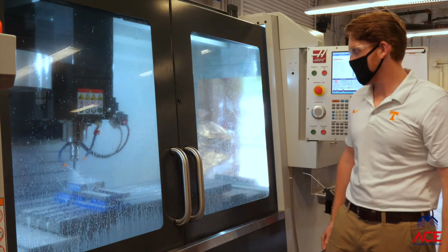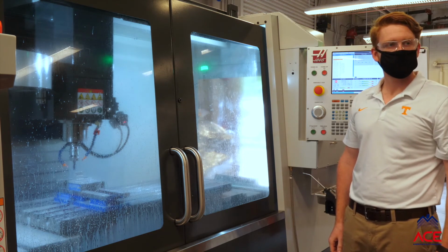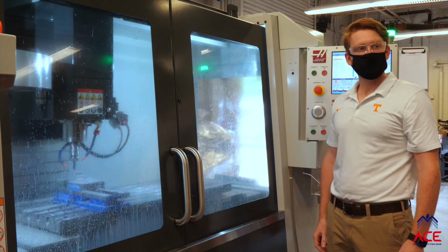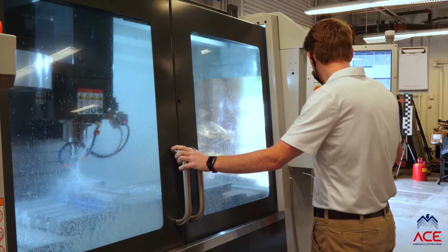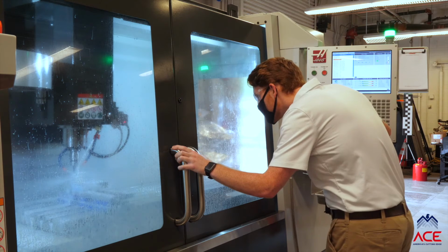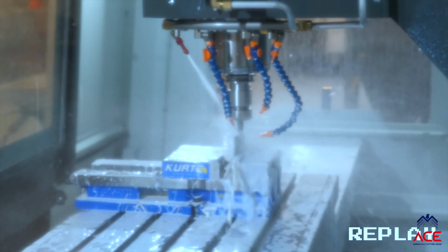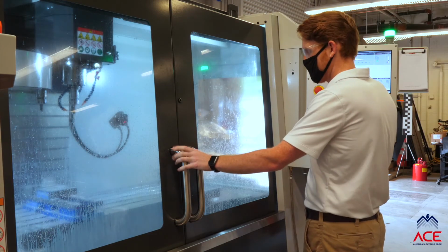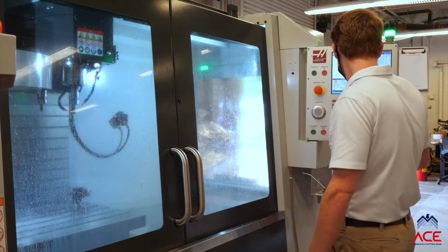Okay, so the cut we heard there was unstable. That was chatter. We'll next complete a stable cut, and you will hear the difference. Then we'll take a look at the surfaces that were machined to compare them. So the only change between those 2 test cuts was spindle speed.